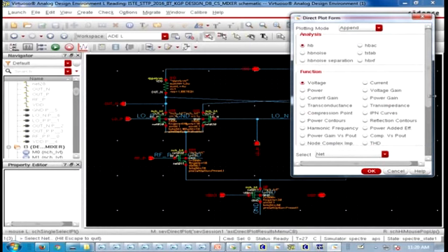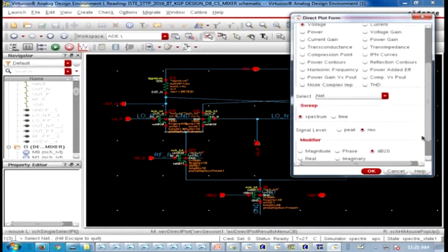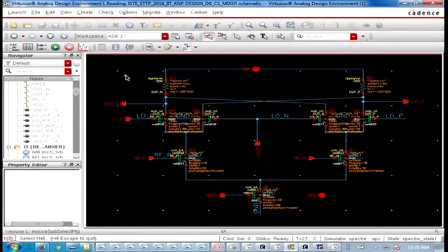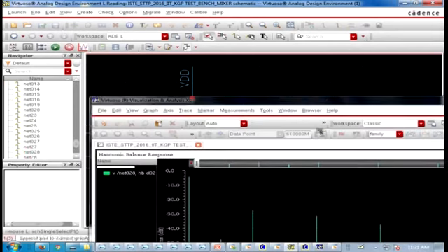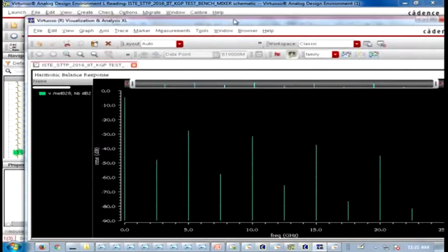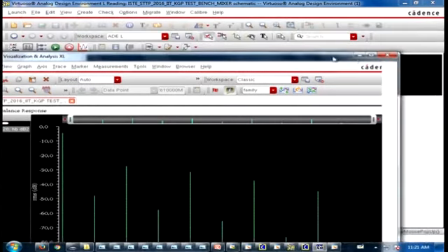One thing is that this normal HB analysis also will give you the local oscillator to IF band rejection. So this is around minus 48 or 50 dB, which is leaking. It is less, which means it should be like this. So minus 48 dB is quite acceptable. Anything less than minus 40 dB is fine.